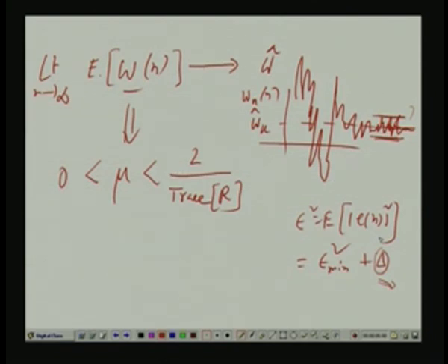That means there is actually a training phase in an adaptive filter, during which the desired response Dn is given to the filter, and the input Xn is given. So, you find the output Yn, then find En, and use the En in that LMS algorithm to get the next filter weight Wn plus 1, and so on in the iterative algorithm. So, during this phase Dn is available, and you train your filter so that from Wn to Wn plus 1 to Wn plus 2 you get a better and better estimate of the filter value, so that at least in the mean the filter weights converge to the optimal value.